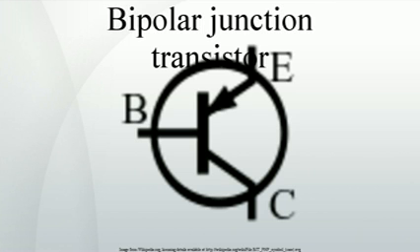Typically, the emitter is heavily doped compared to the other two layers, whereas majority charge carrier concentrations in the base and collector layers are about the same. By design, most of the BJT collector current is due to the flow of charges injected from a high-concentration emitter into the base, where there are minority carriers that diffuse toward the collector, and so BJTs are classified as minority carrier devices.